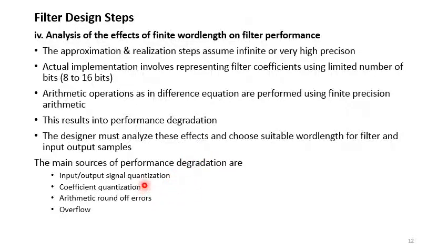Again, coefficients: theoretically we say we have coefficients with very high precision, or infinite values, but practically we have to represent these coefficients by some finite number of bits, so it will result in some degradation. Again, the arithmetic round-off errors will be there. And the other error includes the overflow error.